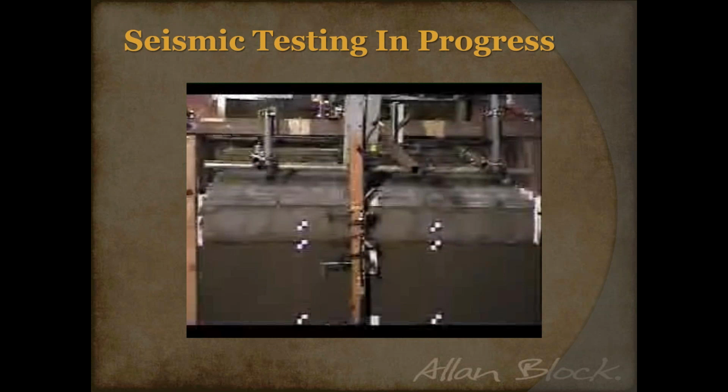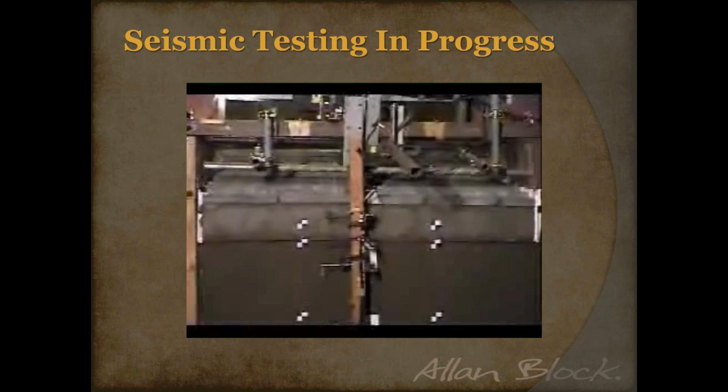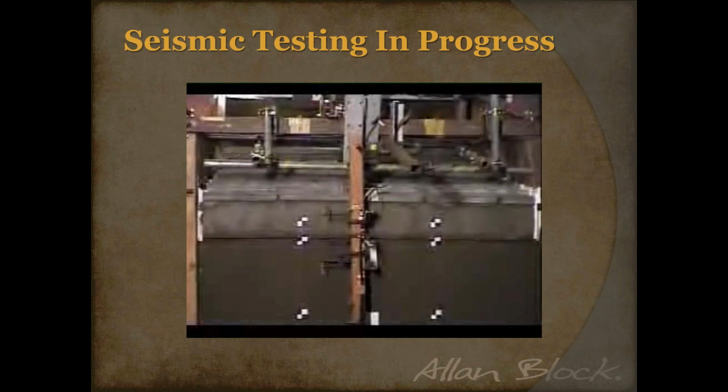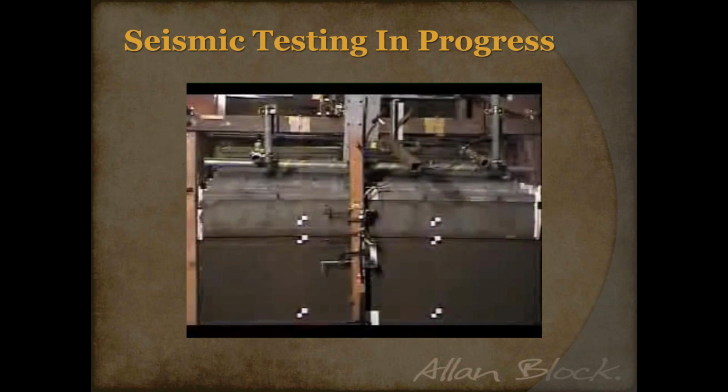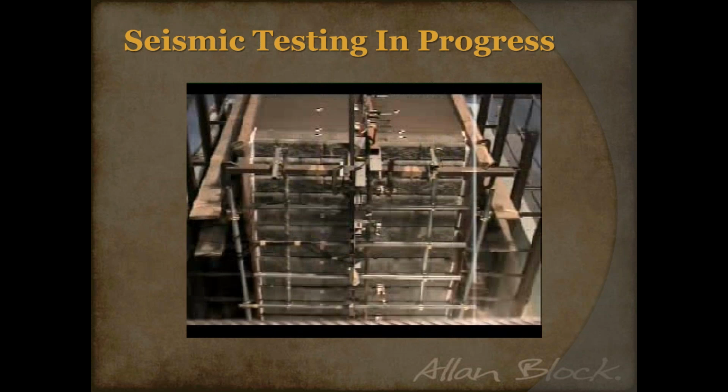One thing that benefits these walls, in not only seismic movement, but any sort of movement, could be frost heave, that sort of thing, is that they are flexible. Obviously, other types of walls, such as a cast-in-place wall, would probably see some significant cracking and might crumble altogether in this sort of event. But since the blocks are able to flex and move with ground movement, it allows the wall to stand strong.